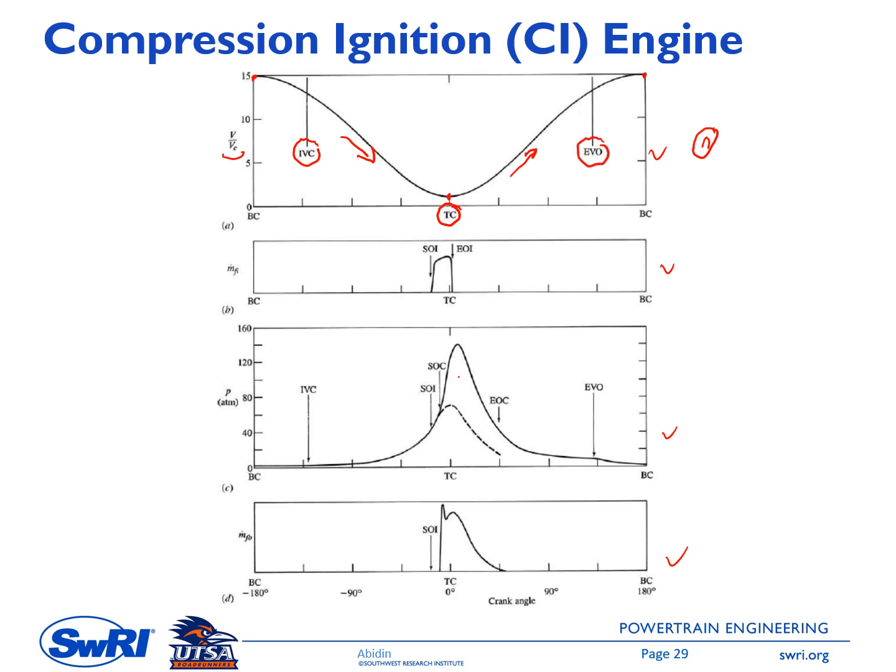So the diesel fuel is injected somewhere at this point. You can see in here on the second figure. This is the SOI, start of the injection. This is the profile of the diesel fuel injection. Okay, so it will take a time to hit the maximum diesel flow, and this one is EOI, end of injection. So this shape is sometimes called the rate shape of the fuel injection.